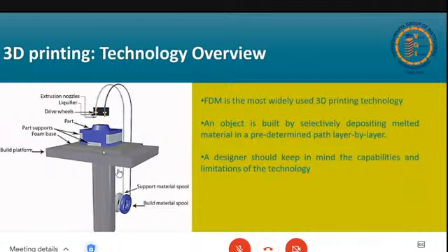Also, it takes twice the amount of time to print. Let's suppose you have 10 layers to print, it will print, let's suppose, in 1 hour. So if you are reducing the layer height by half, it will take twice the amount of time to print. So you will have to basically optimize between your time and the quality that you get.